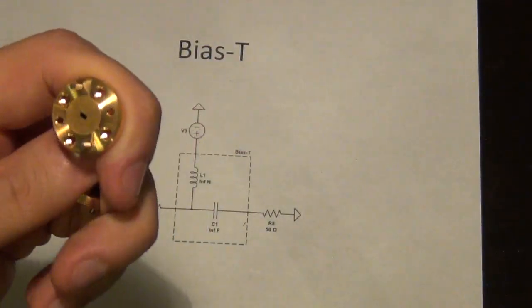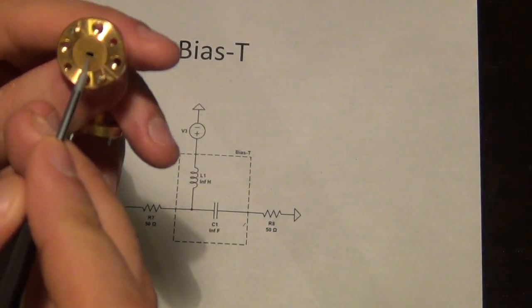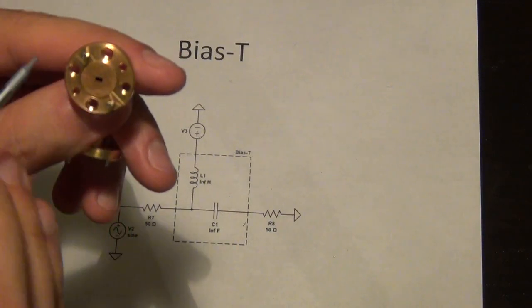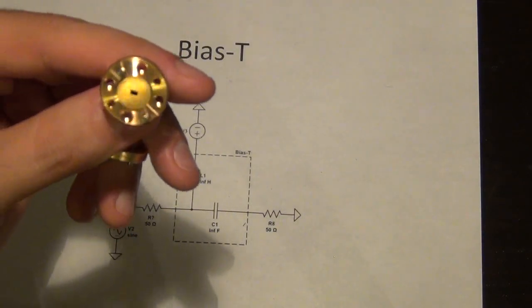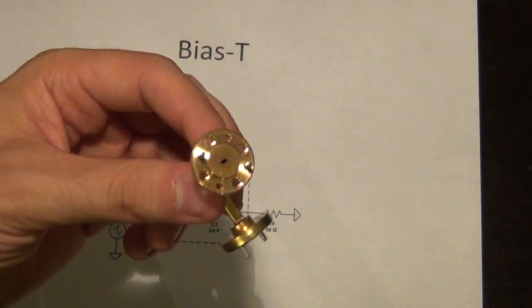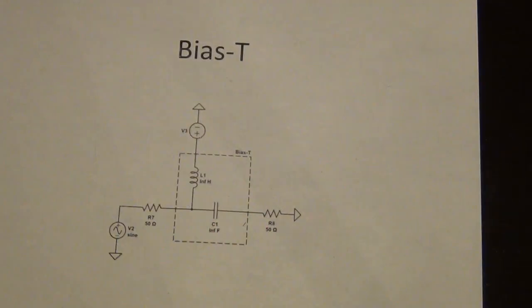Waveguide pieces are fairly, they're less sensitive, but of course you can imagine that the edge of this connector is very sensitive. If it gets chipped or if it gets pushed, or if it changes shape, then of course it will not have the proper characteristic impedance, and it will have attenuations that are unexpected, and you have to be very careful with these.